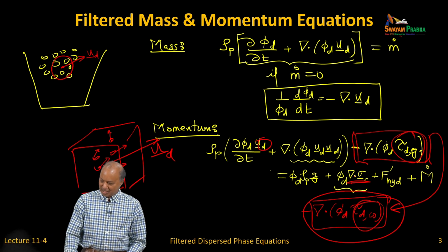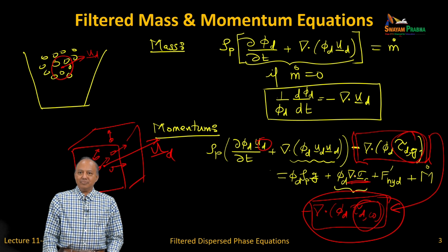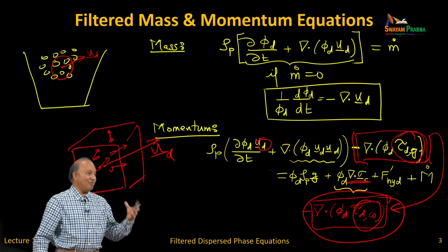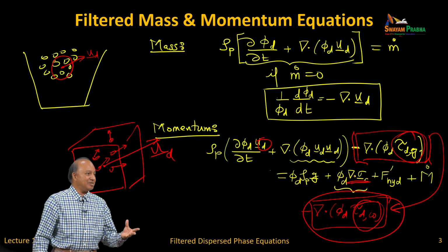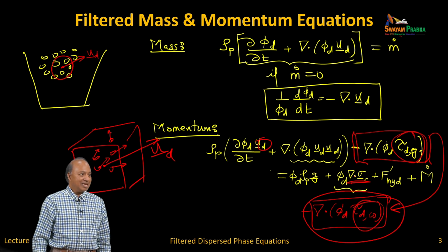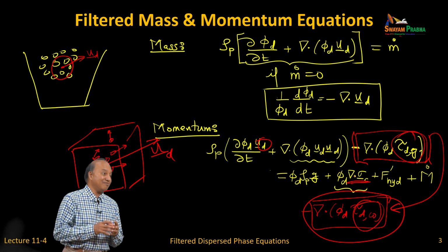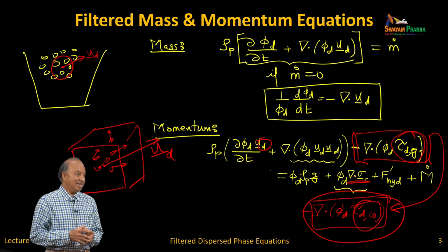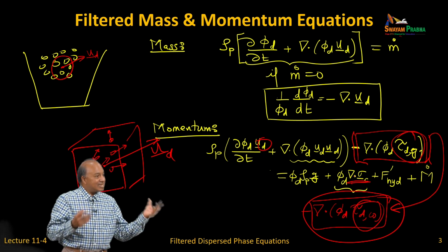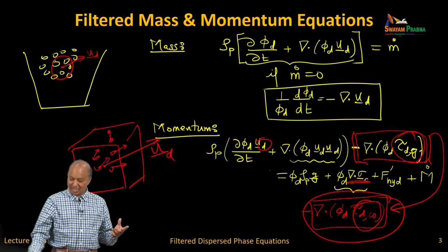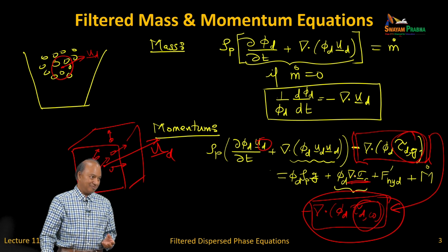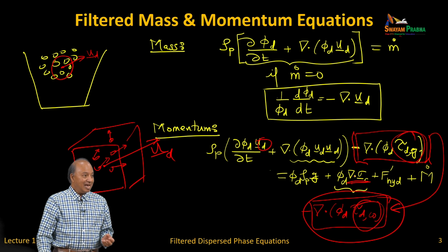Going back to your question, sigma c is, remember, this is not d, it is c. So, the divergence of fluid stress is the viscous force. I am saying this is the resolved scale viscous stress. In other words, you remember we have smoothened it, we use either the blue curve or the green. The stress associated with that filtered velocity is the sigma c. Divergence of it is the viscous force that appears in the Navier-Stokes equation.